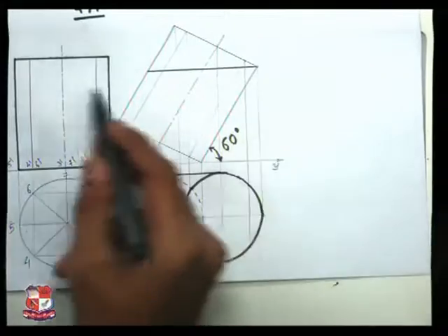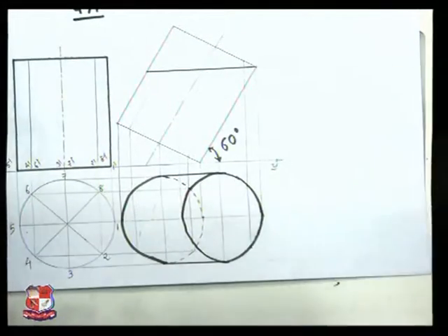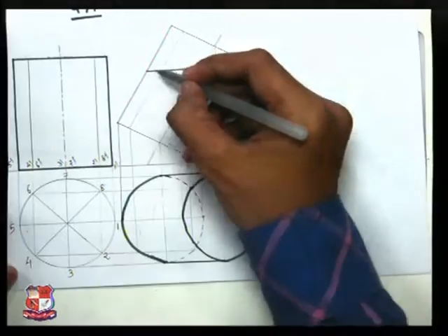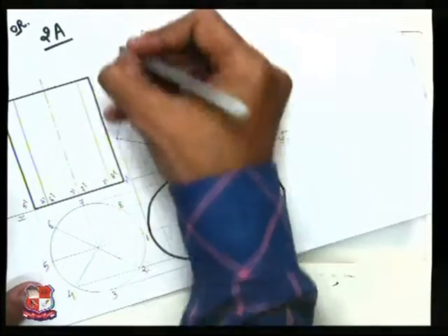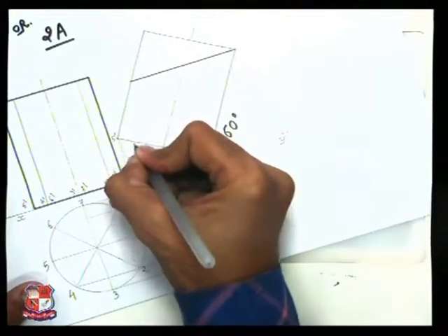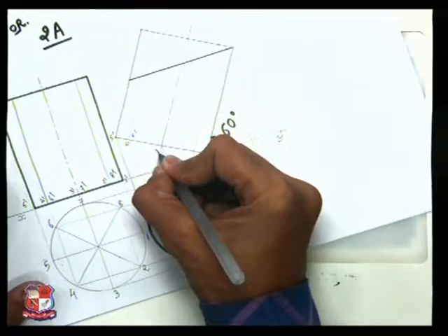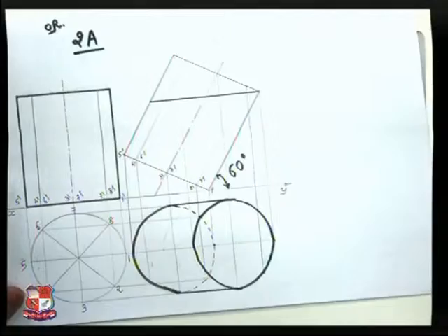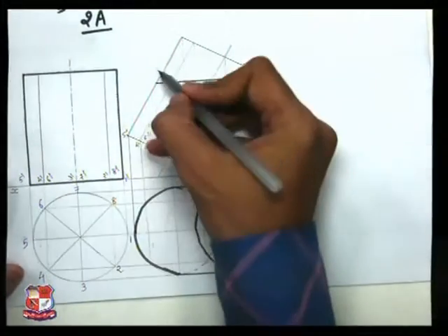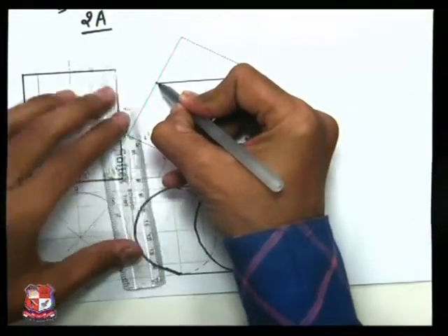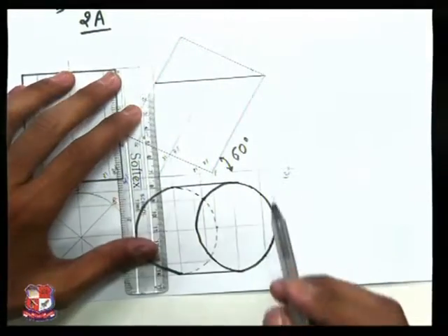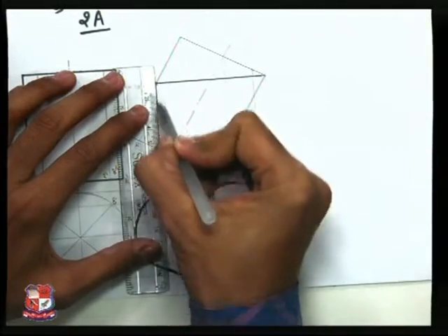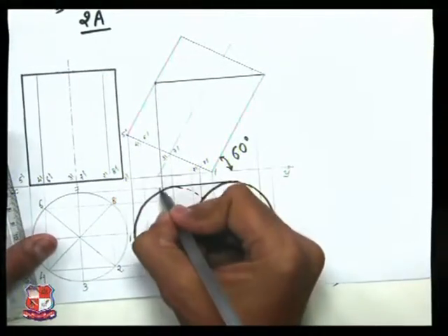Think about the layer of water which is there over here. So for that, let me pick up the points of intersection between this water layer and this generator. This generator is, say, point number 5 dash. Here is point number 4 dash, 6 dash, 3 dash and 7 dash, 2 dash, 8 dash, and this is 1 dash. So on point number 5 dash, here one point is there. From this point, that is the intersection of the 5 dash generator and the water level, draw a straight vertical line like this. This is a projection line.